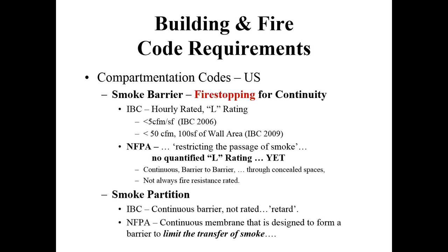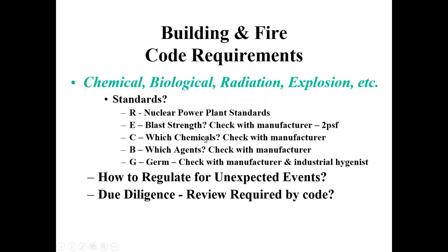Secondly, the L rating needs to be specified as well, because the L rating is the suitability for use statement of the Firestop product in a smoke-based application. The ASTM standard will always win, or other standard, could be a UL standard, could be another standard, but the key thing is that the industry standard that says something serves a certain purpose will win in a court of law over a contractor, distributor, or manufacturer statement saying, yeah, sure, this stuff will work in that application. So be careful about that.